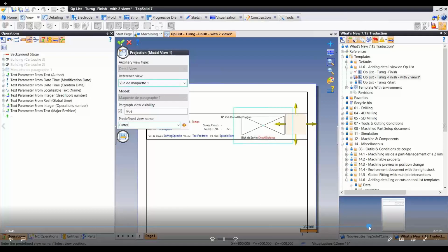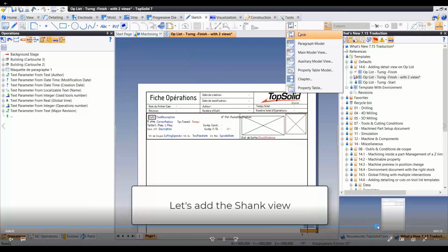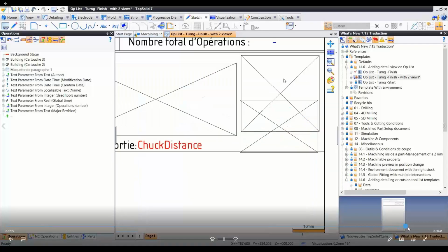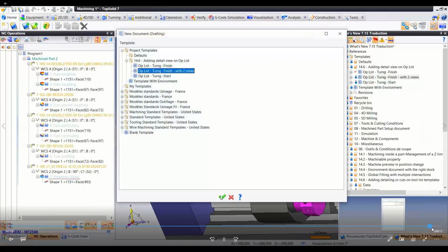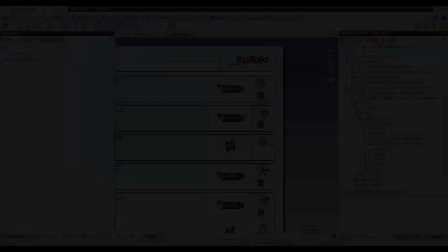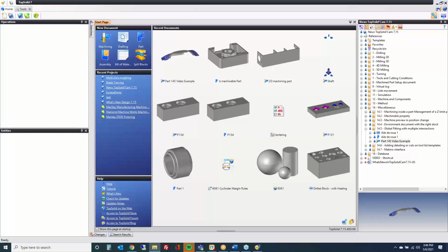So when you're editing it, you now define it by name. You add another auxiliary view. Make sure you update the name of the auxiliary view to shank or whatever it is you call it. And then that's it. You adjust, and now when you run it, you see you get both. So there's some work to be done, but once it's done, you have a very nice setup sheet. Cool. Okie doke.